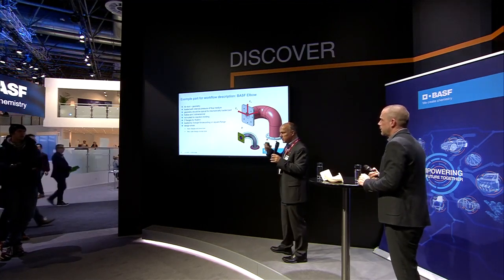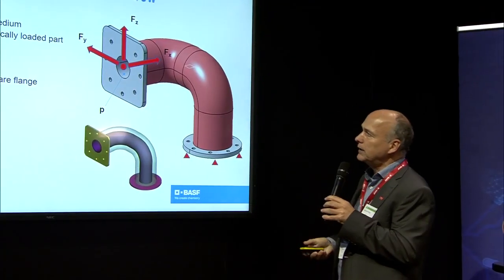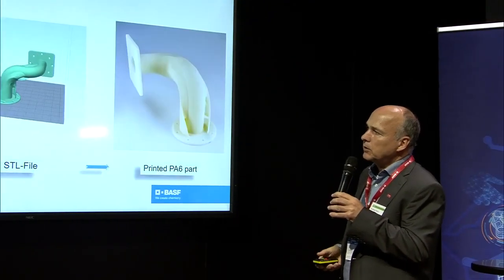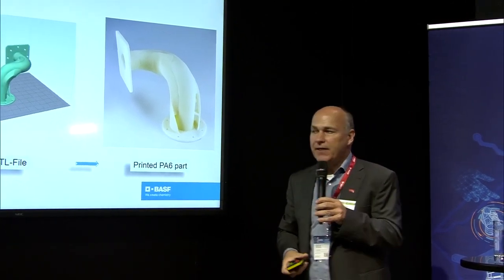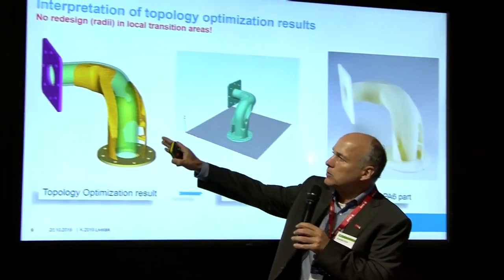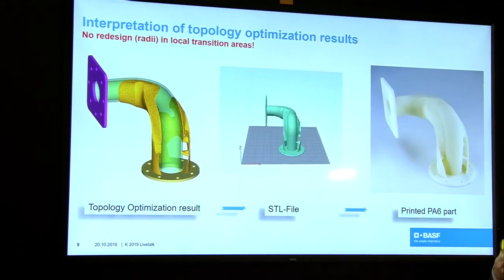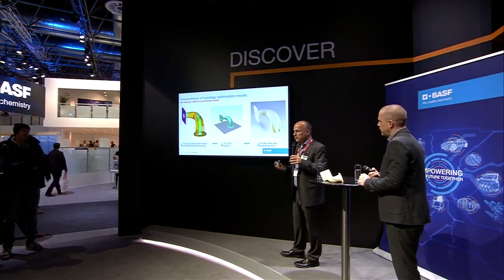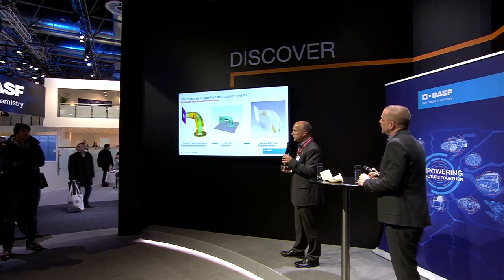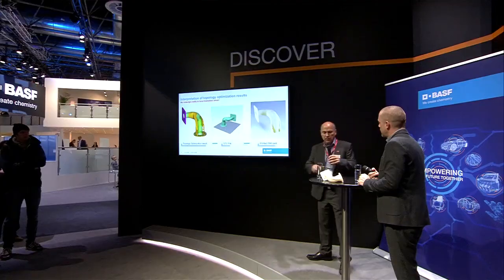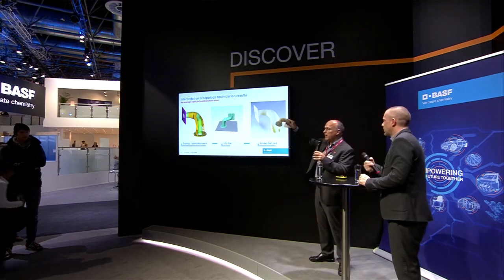Of course, everybody is thinking about ribs, but forget about ribs in 3D printing. We use a technology called topology optimization, and then you get a reinforcement that looks basically like that. This is a kind of organic structure, and this topology optimization method is based on a biologic approach. It mimics in an algorithm the growth of bones and of trees, and so it makes optimum structures, as you can also see in this part. Maybe later on you can have a look at those organic structures.